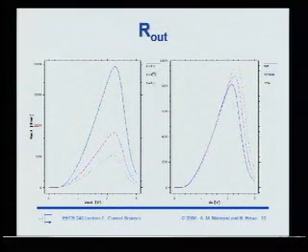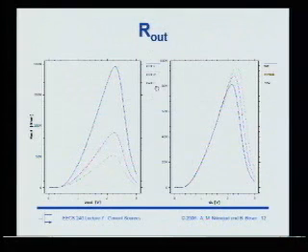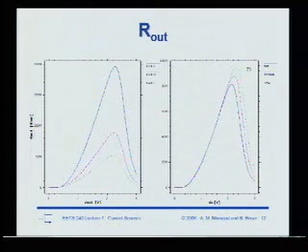So this is as a function of K, so obviously you want to use a large value of K here. And then this is as a function of just process. You can see on the low side, the process variation is actually pretty minor. This is kind of the triode region where they all more or less look the same. And even here, the process variation is, let's say, 30% or so for this device.